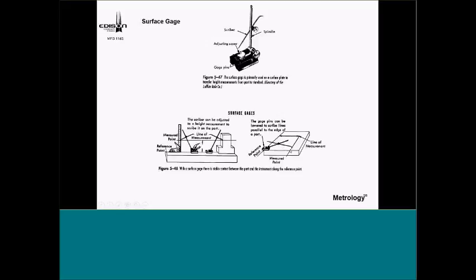And then to use a scribe and coming through here, I'm drawing a line measurement that's parallel to my reference point. Measured point, reference point. Again, they have gauge pins that come down that will push down in there to run parallel against the edge.